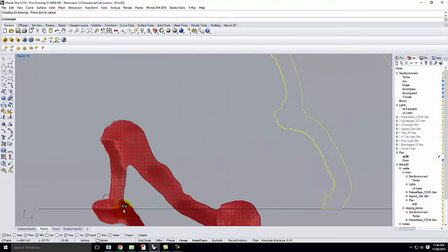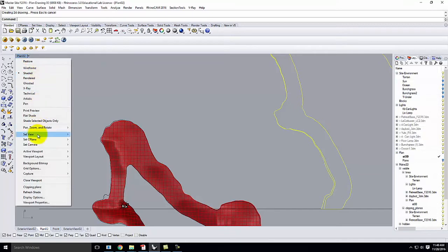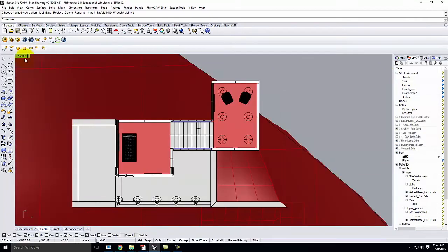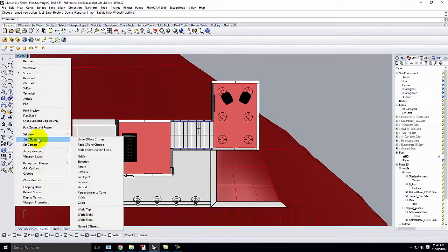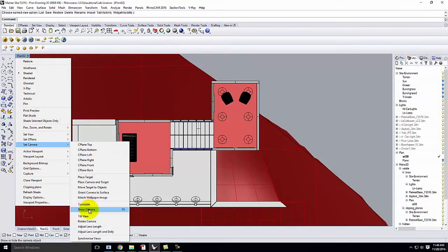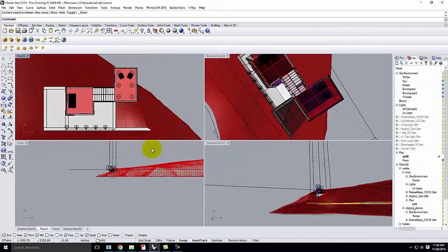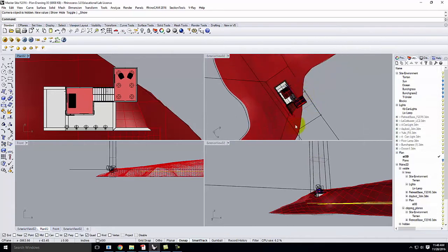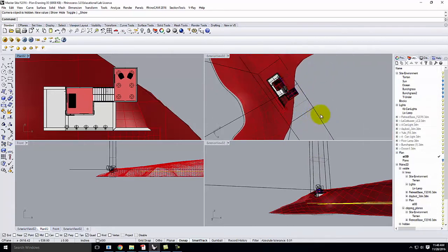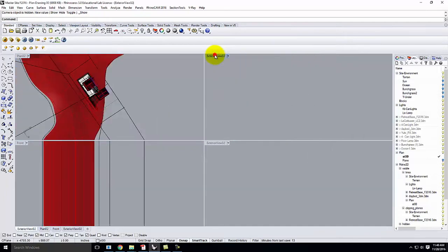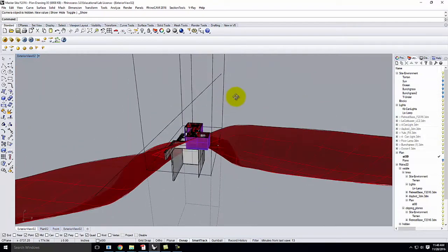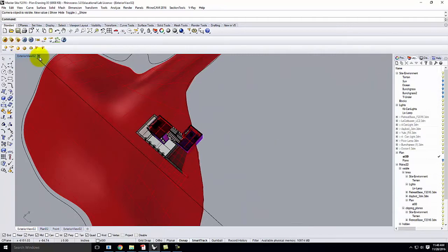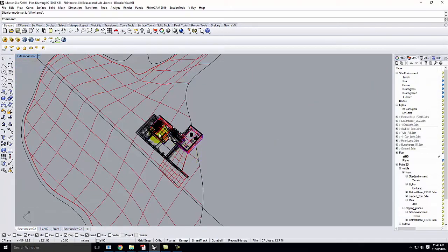Now, I failed in doing this to draw the rectangle for the view, so I don't know how large it is at this point. I could trim it off arbitrarily, or I can come back to Set View, Plan 02, and from here I can go to my Set Camera, Show Camera, and then look at one of the other views where I should be able to get the 3 targets of the camera. And so let's make exterior view here big for a second. And let me show this as wireframe.